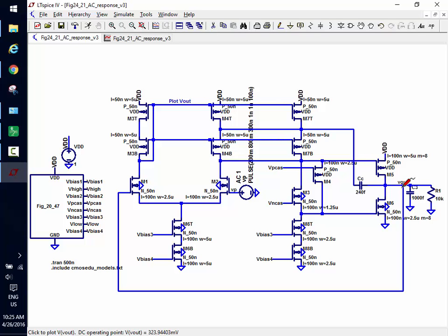Does everybody follow that? If I put a 100K resistor here in series, I would get the same waveform across the output. However, if I connected the source with the 100K resistor directly to the load, it wouldn't. It would attenuate it by a factor of 11. Plus there would be an RC time constant. I don't have that issue here when I put the buffer in.